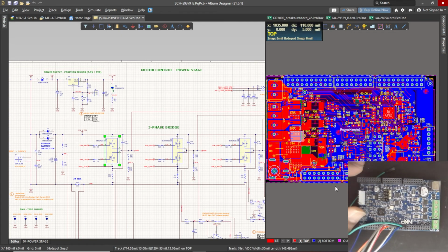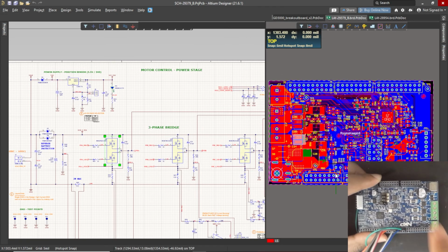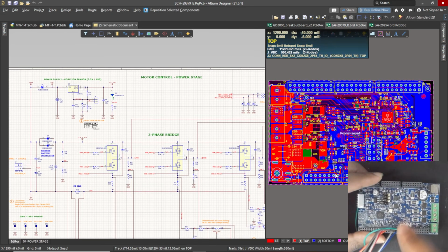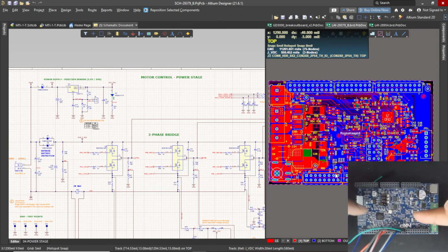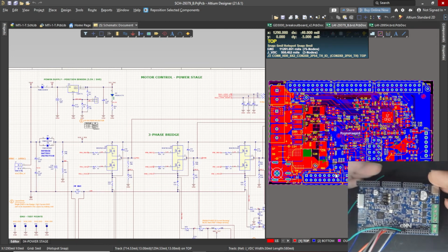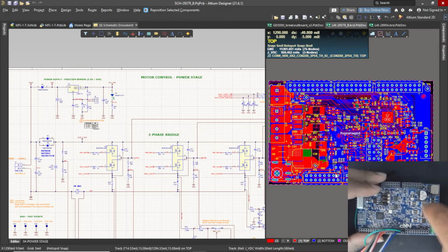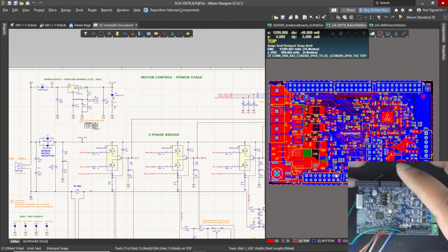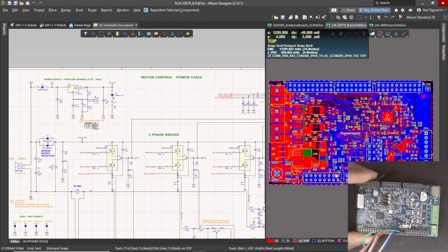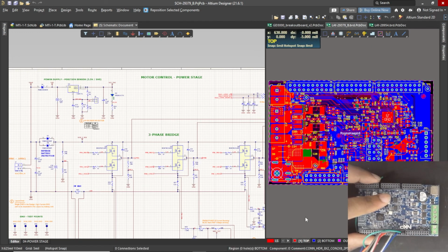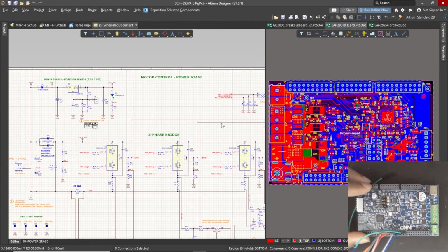So this is one board that I'm really looking forward to getting working shortly, and that's how I'm actually improving my PCB design: by studying these boards, buying the components, and measuring based on the oscilloscope readings and multimeter, and putting my probes in the right place to really understand how things are switching and stuff like that. So that's the next part of where I'm going to progress.